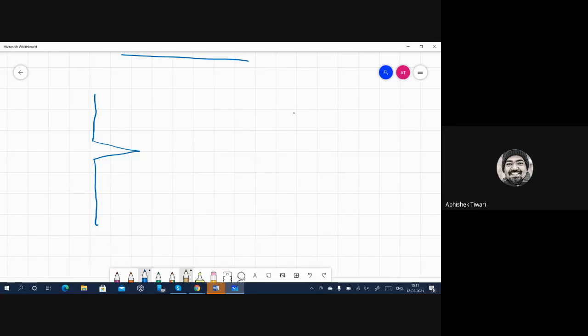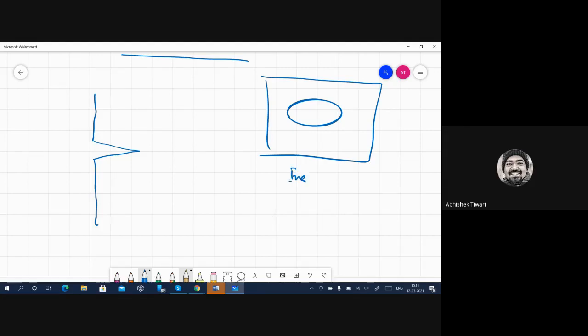In fracture mechanics, it actually began if you have a hole in the system. If you have a hole, what happens? Then Inglis gives the stress concentration factor, if you remember. So sigma at the tip or near the hole will have a magnified value in comparison to what you have applied on the system.